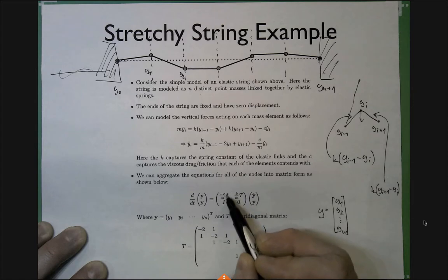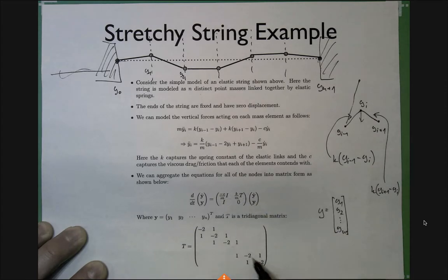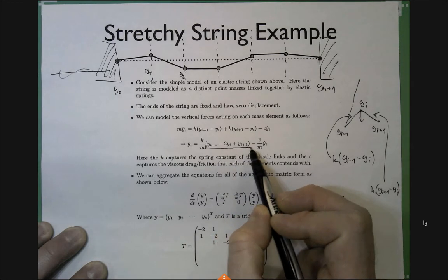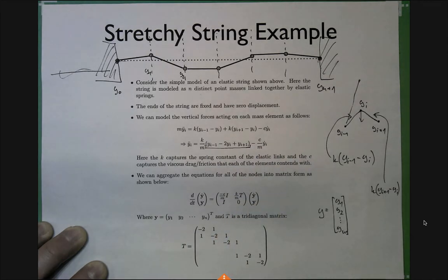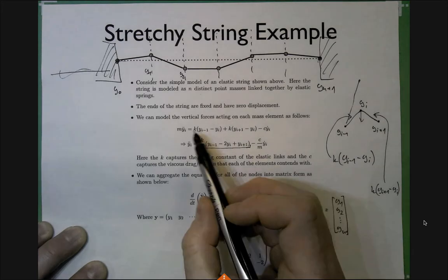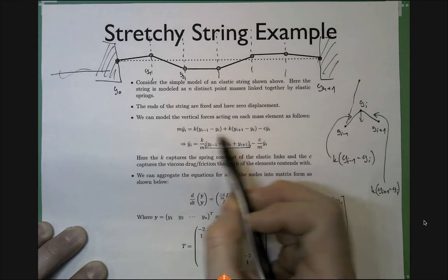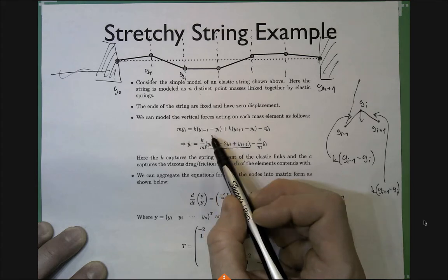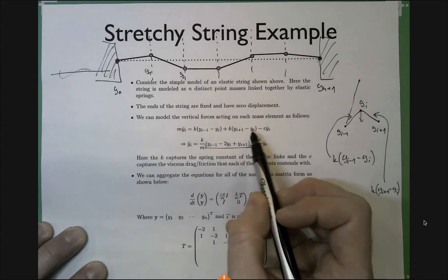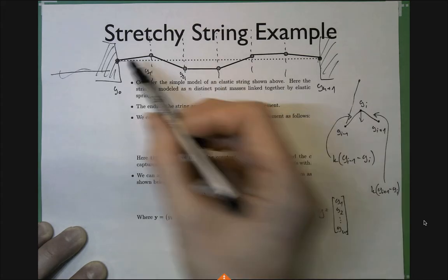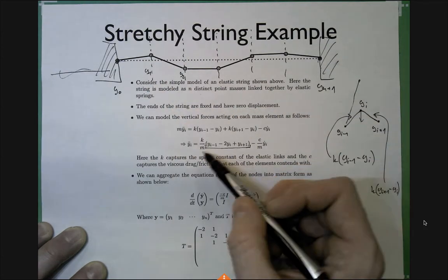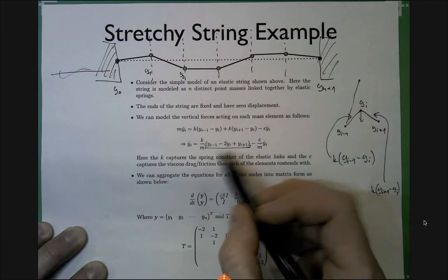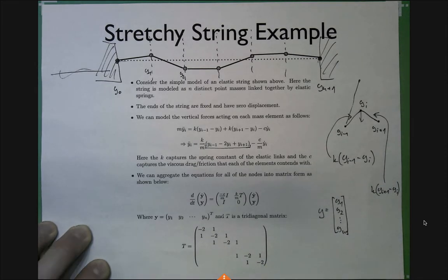So these are the damping terms here, and this T is essentially a Laplacian matrix which has this kernel. So that's exactly this stencil here. We have seen this before, the Laplacian stencil, and you will probably see it more and more. So that's just summing these two force terms together, okay? y(i-1) minus twice yi, because it's here and here. We assume that all the spring constants k are the same for all the springs, so we can just put it together and we get this simple stencil here.